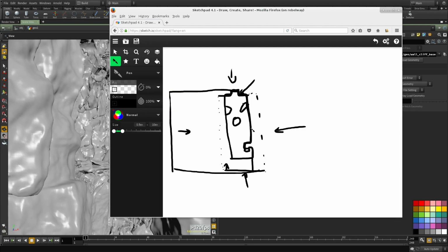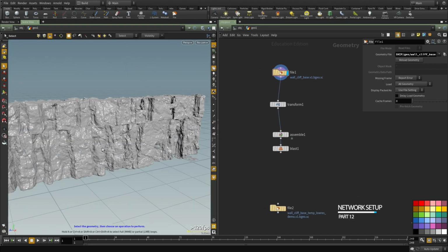If we take all these 6 volumes and intersect them together, we're going to get the information we need. And this is only feasible using VDB volumes. It is feasible with Houdini volumes, but this approach only works with volume because we're going to be intersecting 6 volumes together. But we're not going to be doing them all at once. We're going to basically take the geometry and create a bounding box around it, and then for each face of that bounding box we're going to extrude it and then do this projection thing. So let's take a look and see how we're going to set this up.